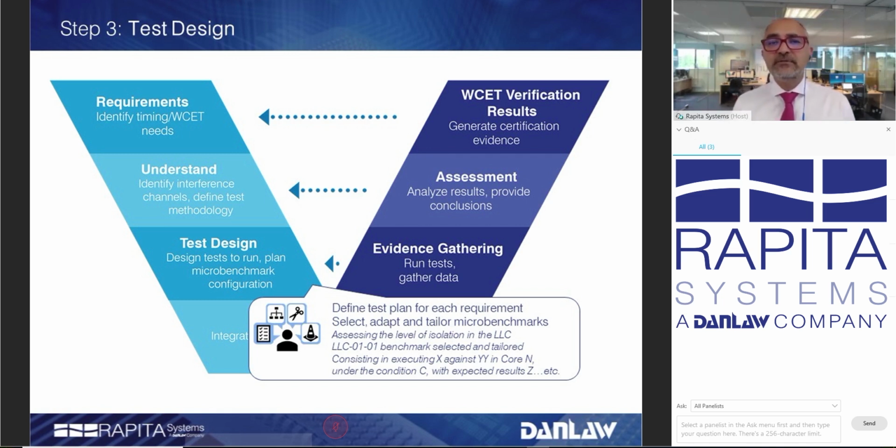And those tests, for example, can be: my application is very highly sensitive, and I expect interference from a particular source for the cache, because of the heavy cache usage. I want to make sure what the potential impact would be if my application did compete on the cache, assuming, for example, that the cache is not partitioned, or even if it is partitioned. So you design those tests specifically to answer those questions and quantify them.